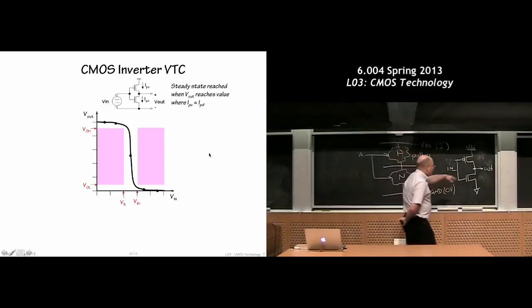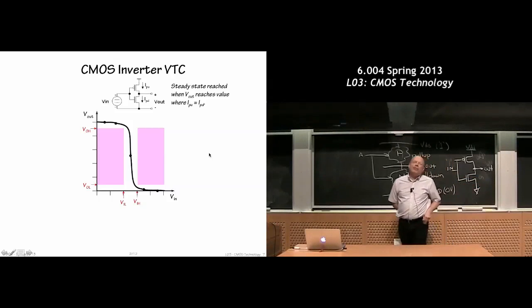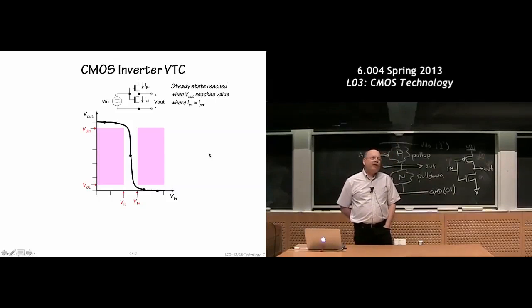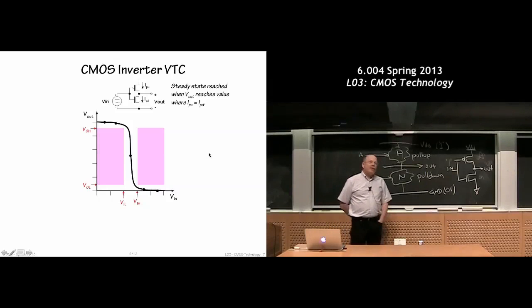at 1. Remember, this wire, which goes off to other places, has some amount of capacitance. So we're essentially storing some information on the output node. And not very reliably, because there's a small amount of leakage current. When I said this device was off, I was lying. There's actually a couple picoamps of current that flow, enough so that the node will eventually get discharged. But over the course of, say, tens of milliseconds, that node will maintain its value.